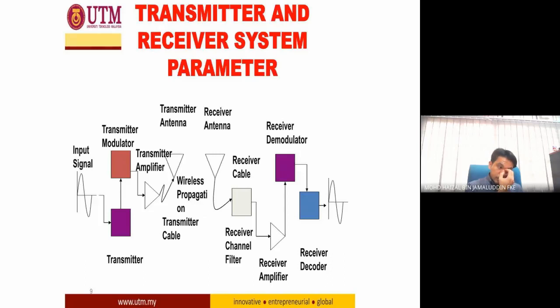So if you look at the receiver considerations in this slide, for example, the minimum SNR for a telephone line is 30 dB. This is the minimum. A TV system needs 40 dB, and good music 60 dB. If it's less than 30 dB, you cannot speak to each other on the telephone. So this is an example of why you use the SNR.